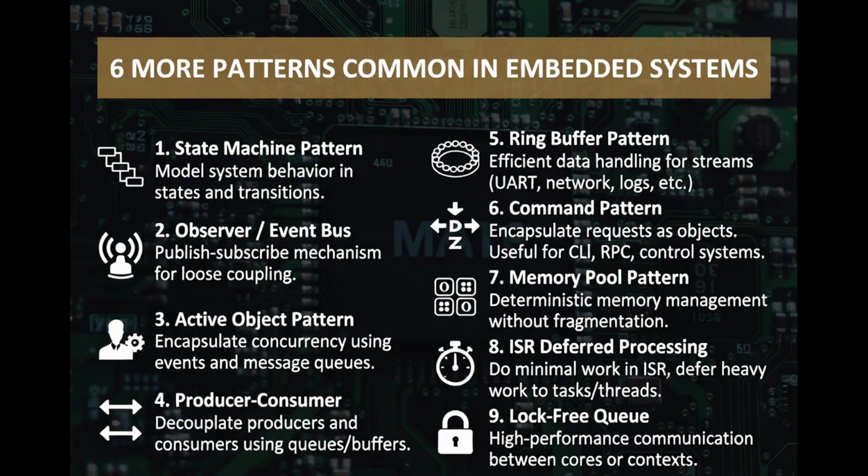ISR deferred processing. Interrupt handlers must remain short. Deferred processing moves heavy computation into worker threads, tasklets, bottom halves, and RTOS tasks.